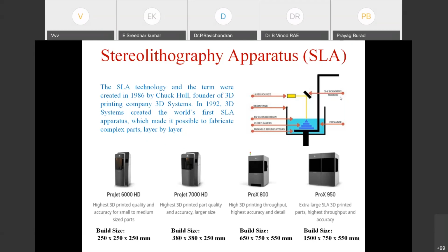And in case you keep it standing, there are possibilities for the generation of more support material, which will end up with an increase in material consumption. Again, the cost of the project will go up. So we have to optimize in such a way as to get a good surface finish with competitive cost. That you can learn by experience.